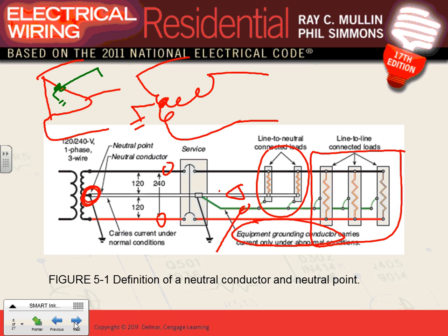Any question about the ungrounded conductor? The phases, the hots. The grounded conductor, the neutral. And the equipment grounded conductor is the one that you tie to the frame of the equipment. In case there is a malfunction, phase to frame, the circuit breaker will trip. Everybody knows the function of these three different conductors. The hots make the system work. The neutral makes the system work efficiently, because I could run hot with ground outside and work it. The white makes the system work efficiently. The green makes the system work safe.